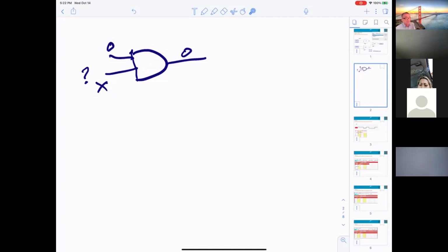The thing is, AND gate, one input zero, output must be zero. If you say you check the other input for logic one or zero, that means you don't understand. This is logic. That means you're not doing any extra work. It cannot be accepted. Okay? And now, if you get this gate here,